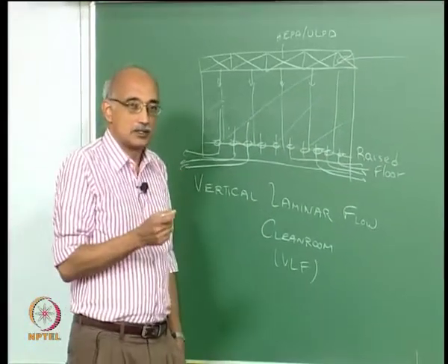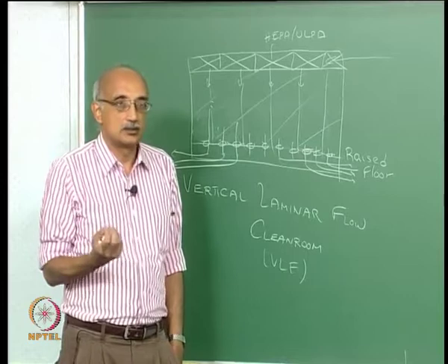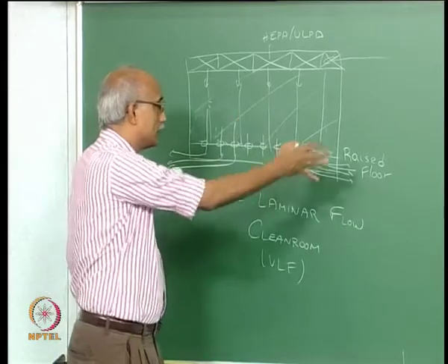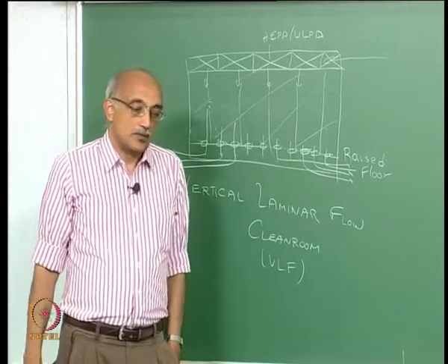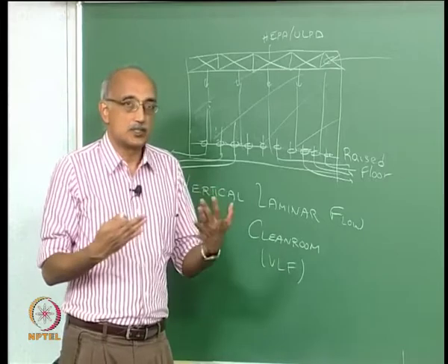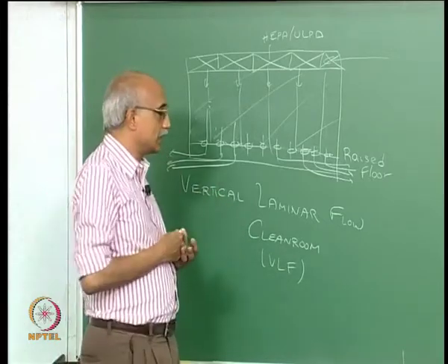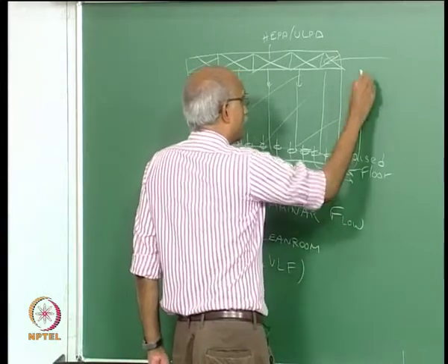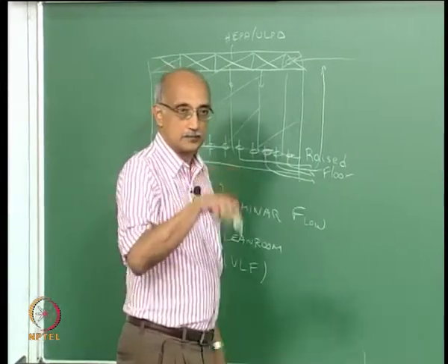The problem is the energy consumption; airflow usage is very, very high. So to operate a clean room in this fashion may provide the best controls on the levels of particles, but it's also the most expensive way to operate a clean room. So instead, what you do is you take some fraction of this outflow and recycle it.